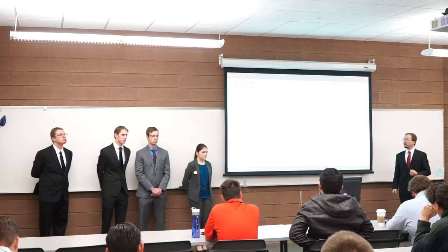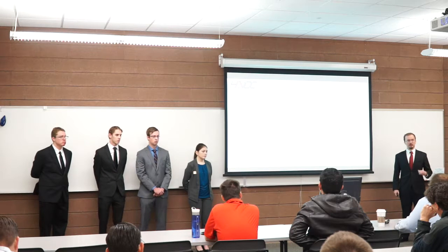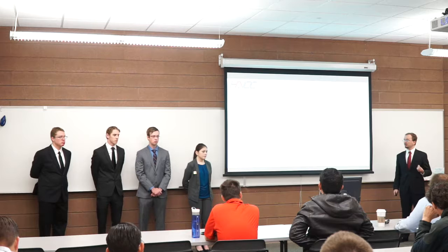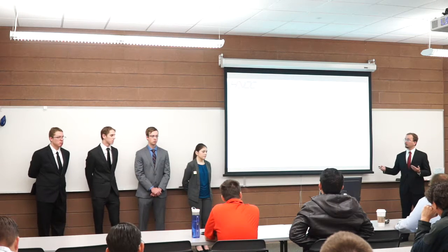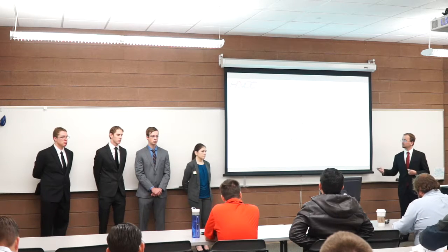Now, for the inverse kinematics. The inverse kinematics, as they are taking task-based positions and turning them into angles, we'll be using trigonometry to grab the angles theta, theta 1, and theta 2. Right here are my equations for grabbing both of those.